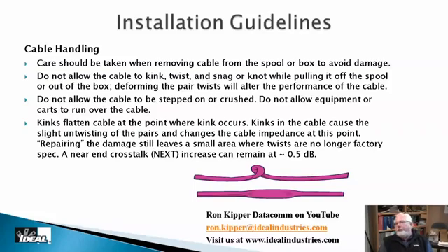And we tell you don't kink your cable, and I'm going to tell you during the process of these classes, if you haven't heard me say it, especially with 10 and 100 Base-T, you can stomp on that cable. It's probably going to work. Now, nobody recommends this as a general rule, but you'll find it's pretty robust. But anytime you deform the shape of the cable, you're basically causing a bump in the road. And the more we do this, the more problems we could potentially have. But as a professional installer, the idea is not to damage the cable in the process. If you're one of those type of folks, that'll catch up to you sooner or later. So again, try not to damage the cable in the process.